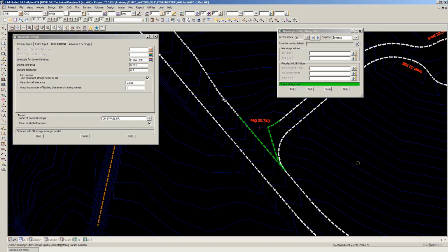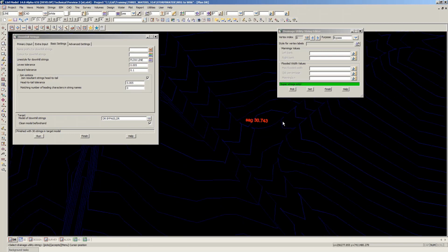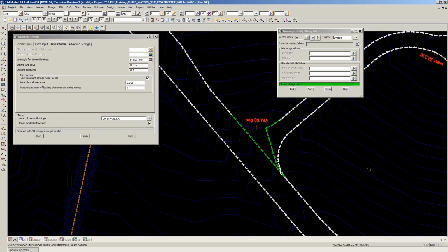In my case, I might choose to have 100% of the catchment flow coming down this straight through line, and at this point and this point, where another node would be on the other side of the road, I could use this option here to set these 2 reaches, from this point down to there and this point down to there, with only conveying bypass flow. And that's easy enough to do.